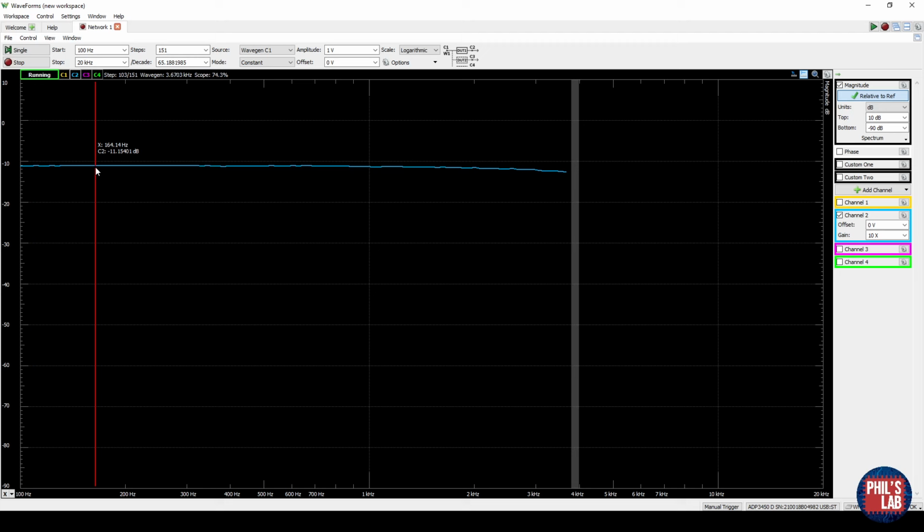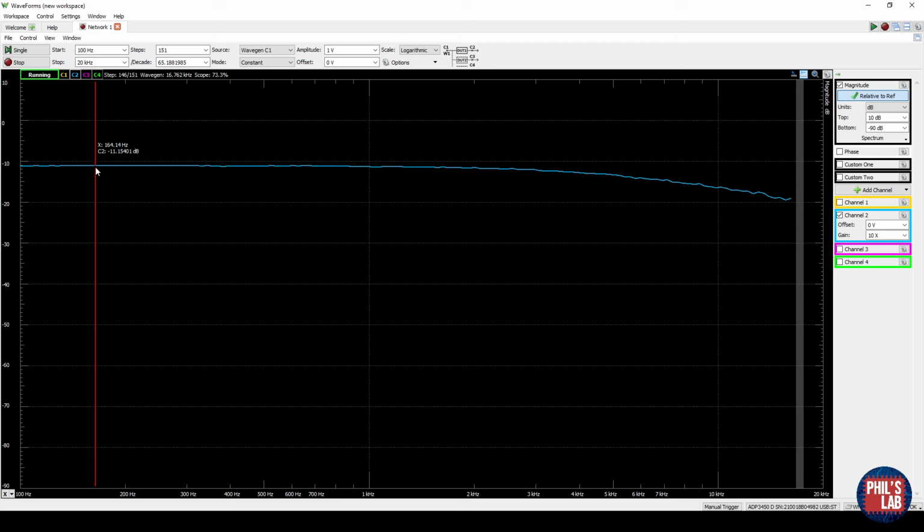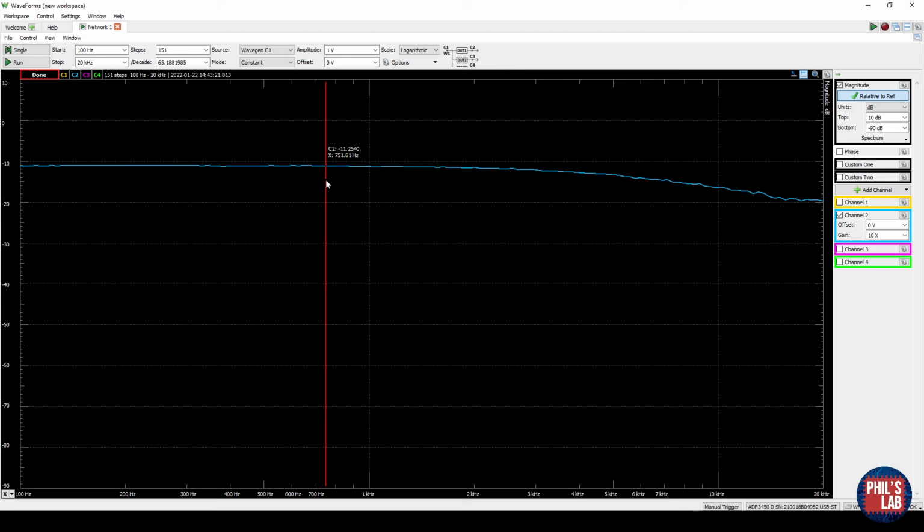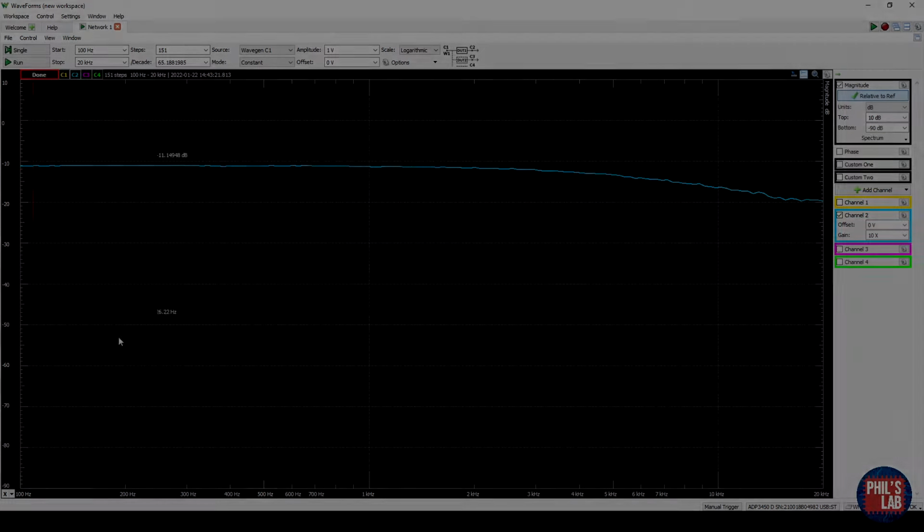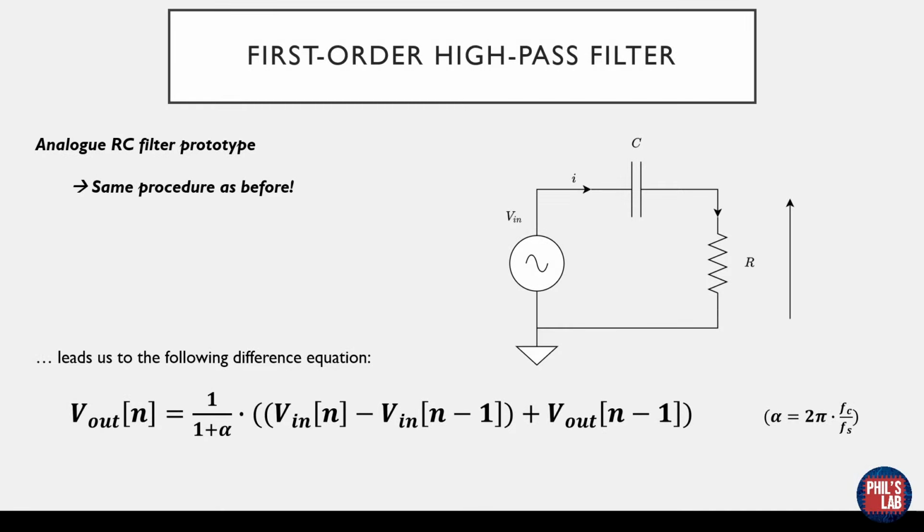We have a variable low-pass filter, even though not a great one. It's a simple first-order low-pass filter. We've done a pretty bad approximation with the Euler method, and we have a working volume control. Now we can implement the high-pass filter in cascade with this low-pass filter, essentially forming a very simple band-pass filter. So now we can try, after we've analyzed this low-pass filter at least a tiny bit, we can move over to the first-order high-pass filter.